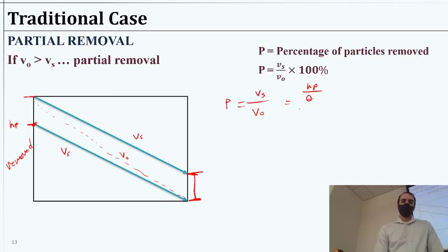divided by our theta, and then V naught is the height of the system. If a particle is at the height of the system, that's our critical design velocity divided by theta. Then what we're saying is the height of the particle divided by the height of the total. And so to get the fraction that is removed, that's how we get that relationship. And that's why it makes sense. We can just simply compare the velocities because there's nothing else that's changing. It's just really the height that it traveled.